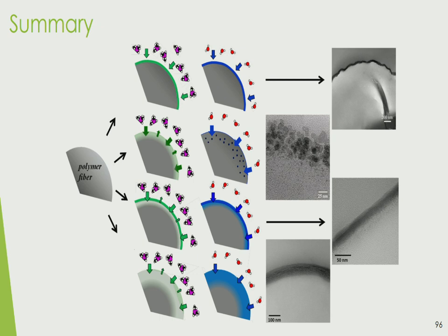Okay, so quick summary. That's a lot of slides in an hour and 15 minutes. All right, so we have our polymer fiber. There are a number of different mechanisms that are happening here. I'm now breaking the infiltration into two things. Generally, you have ones with reactive surfaces, ones with non-reactive surfaces, ones that are really reactive but still allow for a little bit of infiltration, and then ones in which you have complete infiltration into the polymer because of the high polymer volume.